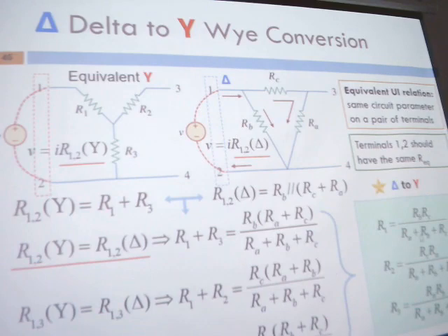Rewriting it, we get these three equations. The resistance inside is our Y connection. Our Y connection for R1, R2, R3 is equal to this. R1 is equal to the product of their neighbors, you can suppose DC is here, so these two are their neighbors, over their sum.